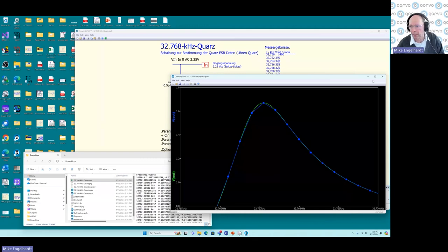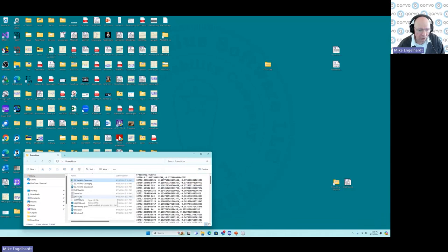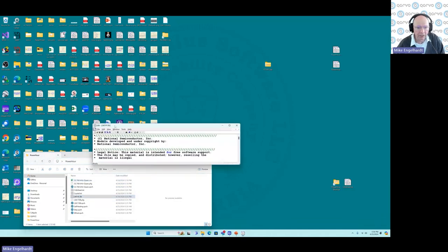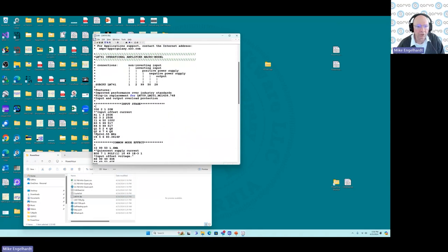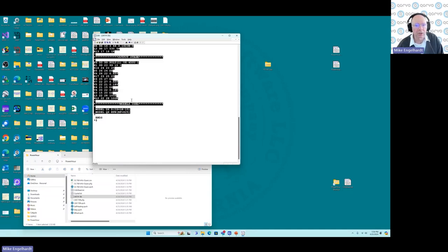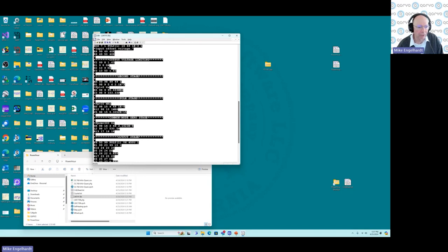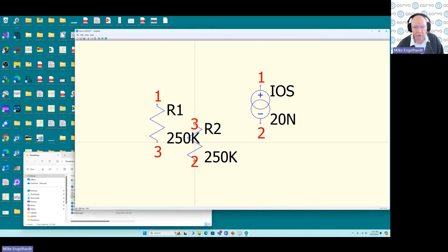All right. So I had mentioned that there is the ability to turn a netlist into a schematic, and that's useful when you have a macro model and you don't know why it runs. So here's a netlist. I type Control-C, and then I come over to QSPICE. I hold down the Shift key while typing Control-V, and then instead of pasting that text, it pastes it as components with all the nets labeled.